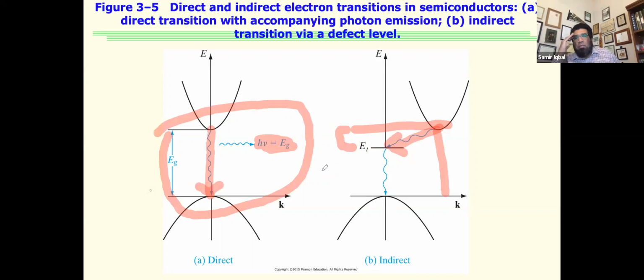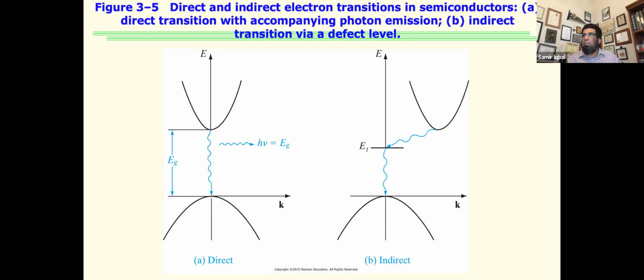So if I were to use a semiconductor material to make my optical system or optical device, I would choose a direct semiconductor material, because all the energy change will be available as a photon to me to get whatever work I'm doing with that material. Does it make sense so far? It's a new concept of direct and indirect semiconductors.